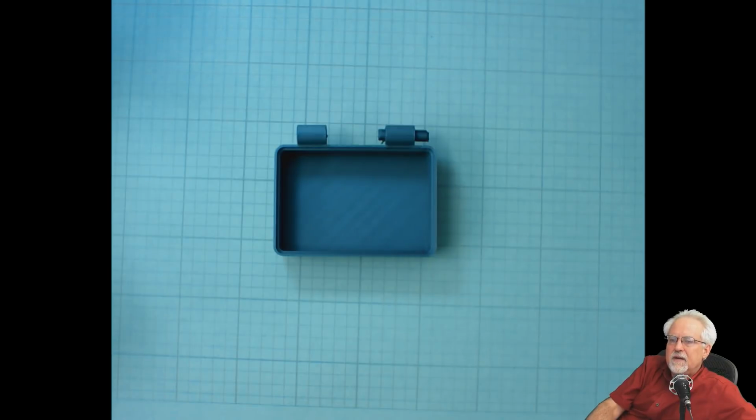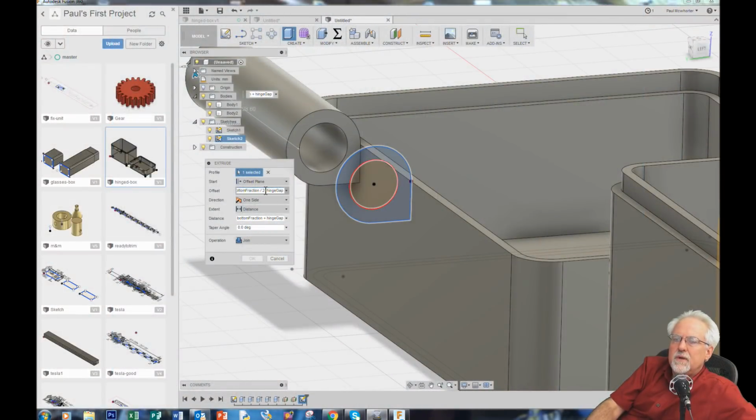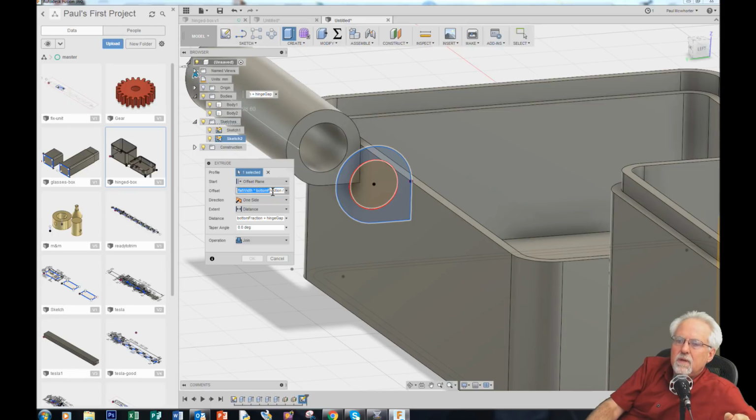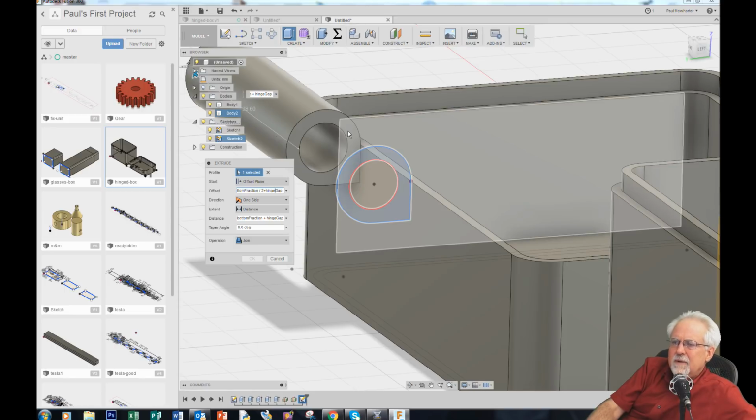So what I just defined here was this point here. I put in here, this is where we're sketching. This is where I want this extrusion to start. Offset, right? Offset how much? The flat width times the bottom fraction divided by 2, that's that gap, plus a tiny amount, plus the hinge gap. So that leaves just a little tiny bit of extra space.